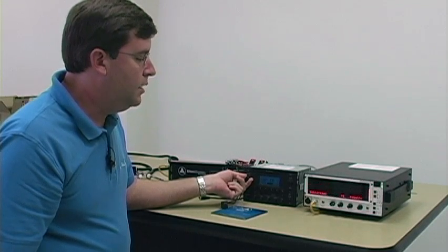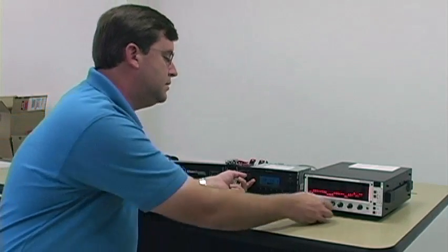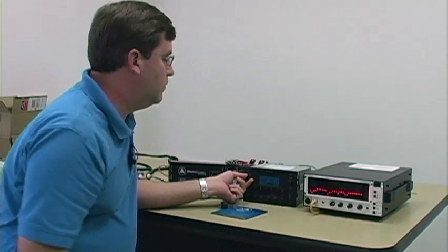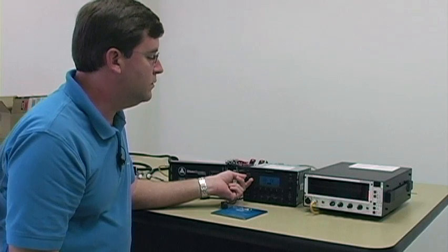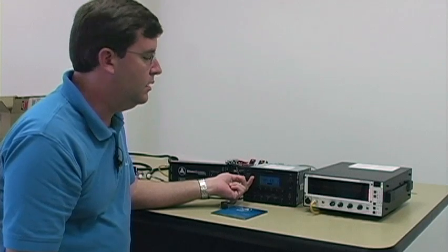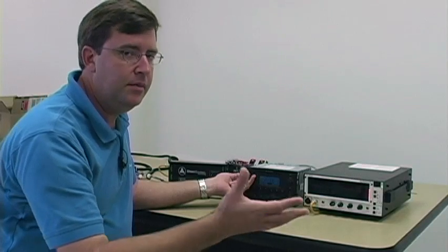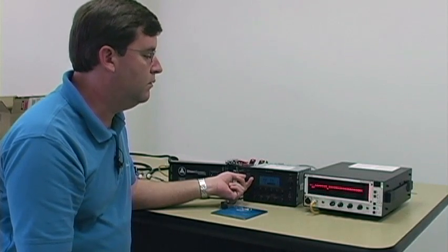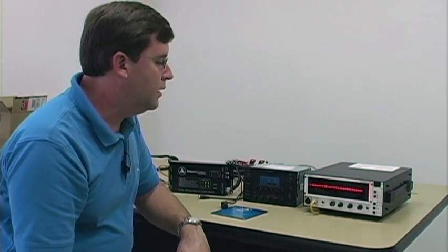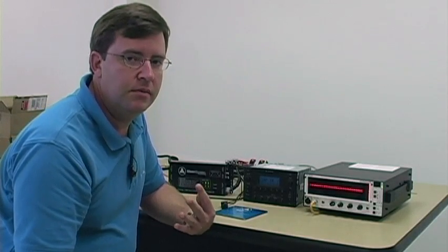What the customer might notice, and may or may not be okay depending on how it's implemented in the system, is that the frequency response can change somewhat at lower volumes because some of these factory systems apply a volume dependent correction effect, and that's usually a bass boost at lower volumes and maybe a slight treble boost. It's really not the end of the world. So if the customer wants to use his steering wheel controls and doesn't want the knob installed, that should never stop you from doing a CleanSweep installation.